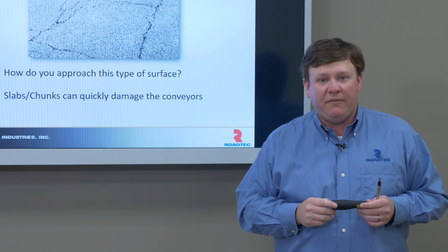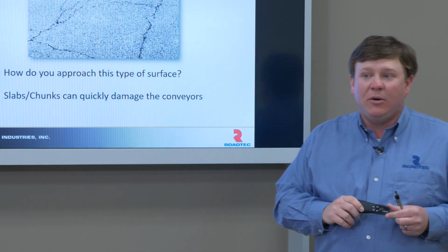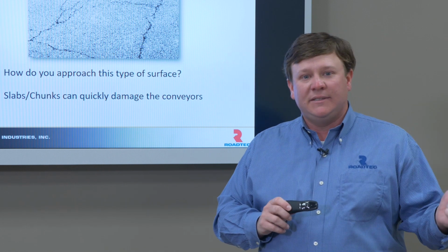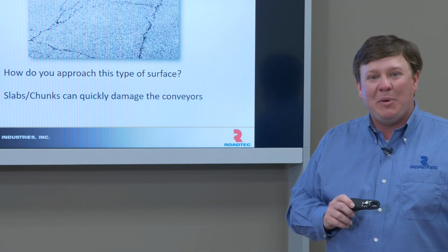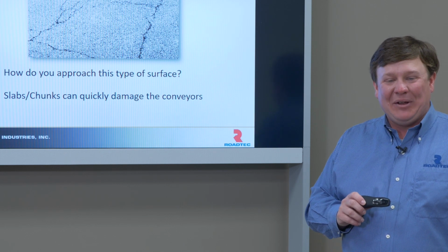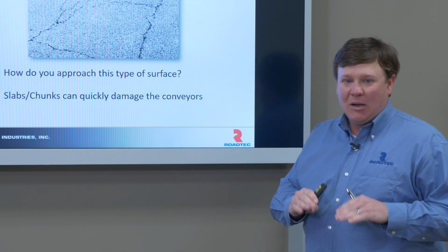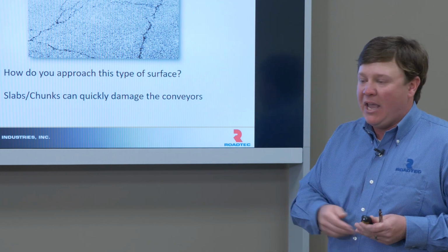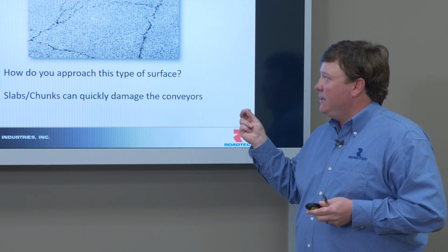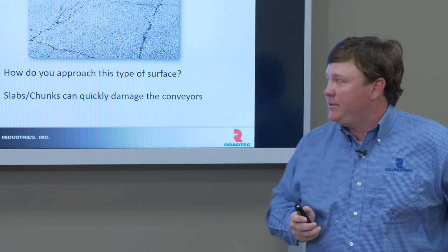That's going to damage the conveyors, and it's going to ultimately create downtime. That's a big deal, especially when you have several trucks of hot mix asphalt and a paving crew right behind you that are preparing to pave. If the milling machine's down, we have an issue. We can avoid this by slowing down, applying pressure to the front mold board, and processing the material slower, so we're not throwing huge slabs of material in, doing damage.